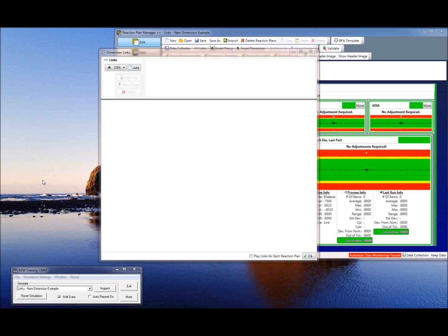Now, there are a couple of different ways you could set the links up to do this. You could set up 6 individual links, and contained within each one of those links you can have the triggers and the actions that handle the copying for you. Or you could have one link that does all of the copying. You can decide how you want to attack it. I'm going to show you how to set up one link that handles copying all 6 diameters into the summary dimension item.